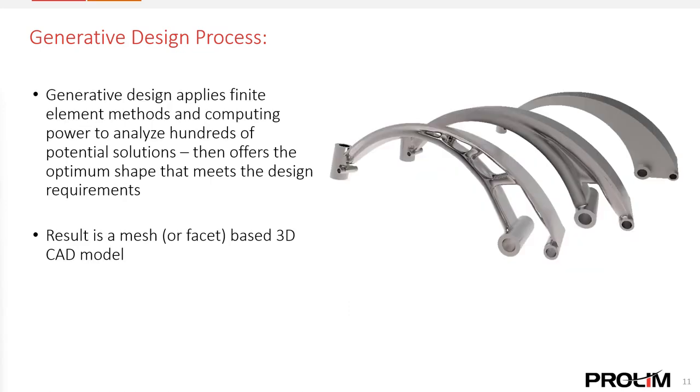Generative design takes into account all the requirements mentioned previously. It then applies finite element methods and computing power to analyze hundreds of potential solutions and offers the optimum shape that meets the design requirements. The result is a mesh or facet-based 3D CAD model.